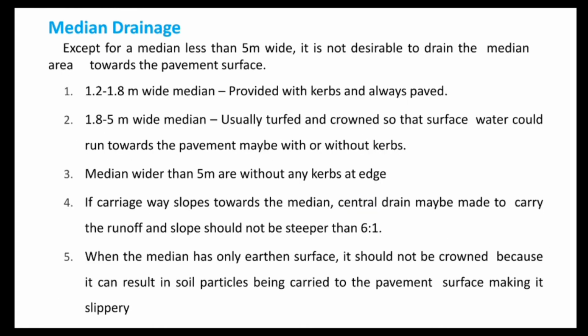The median drainage. Now, except for the median less than 5 meter wide, it is not desirable to drain the median area towards the pavement surface. In general, a 1.2 to 1.8 meter wide median is provided with the curbs and is always paved. A 1.8 to 5 meter wide median is usually turfed and crowned, so that the surface water could run towards the pavement, maybe with or without the curbs.